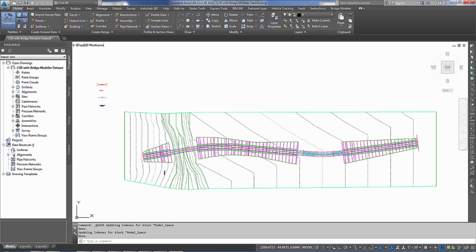To give you a bit of background about this project, we've been asked by our project manager to pass the bridge information that we have to our structural engineers so they can import the bridge into Autodesk Revit Structure and verify and add additional design elements. We will generate the bridge in our design model with the bridge module and then utilize the Revit extension to import it into Autodesk Revit Structure. Make the desired changes, then take the design bridge back to Autodesk AutoCAD Civil 3D to update our roadway model.